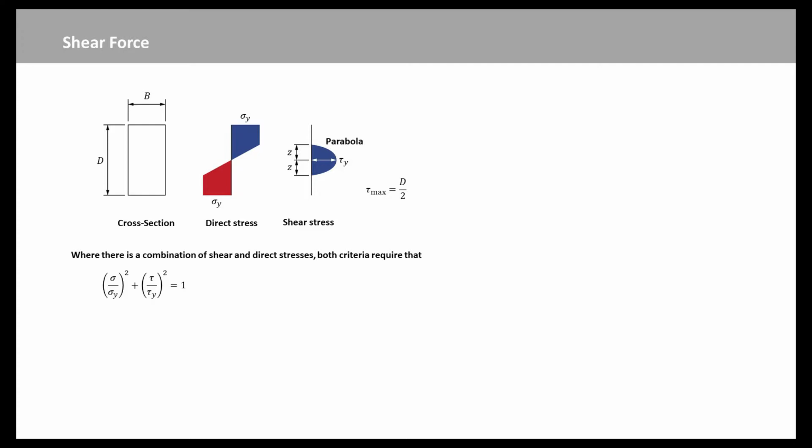The shear stresses have to be 0 at the free edges at the top and bottom of the section, so the direct stress can reach its yield value there. Generally, this yield will spread inwards, leaving a core of material carrying shear and direct stresses. In a rectangular section, theory suggests a parabolic distribution of shear stress with maximum stress at mid-depth. It would be reasonable to assume this still holds in the core and that the maximum stress at mid-depth is tau y when the plastic hinge forms.